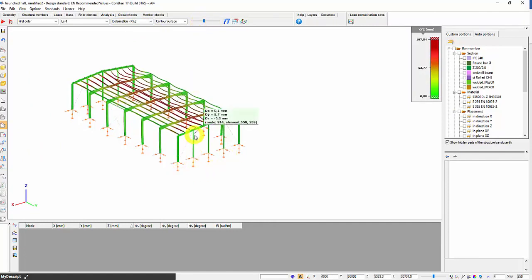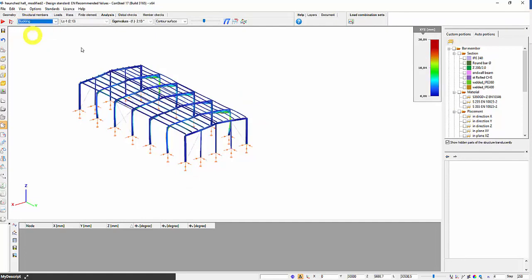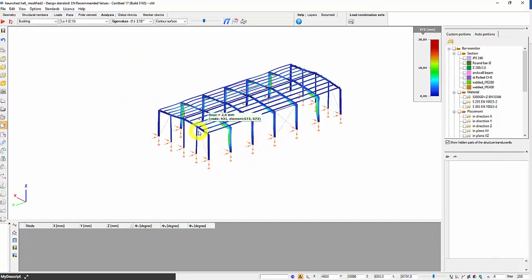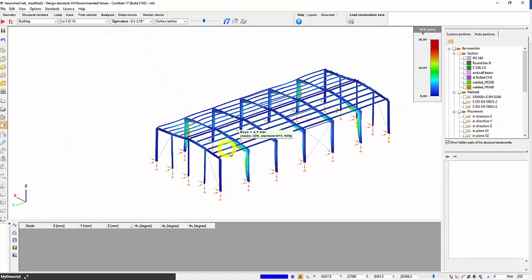However, these elements are not completely eliminated from the linear stability analysis, but all these X-brace type tension rods are considered in the classical way, with half cross-section, because they are usually defined in pairs, even if they are not in the same place. However, to prevent these from buckling, as they would likely buckle under a very low compression load, they are automatically excluded from the model for which the stability analysis is run.